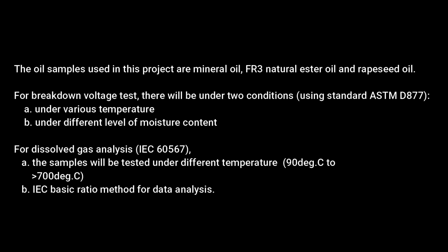Now let's talk about the scope. The oil samples used in this project are mineral oil, FR3 natural ester oil, and rapeseed oil. For the breakdown voltage test, they will be under two conditions by using standard ASTM D877: under various temperature and under different levels of moisture content.